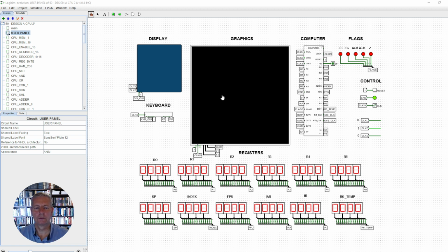I'm trying to do just one thing. I have a command which puts a little pixel on the screen. So the command is PIX, and then the next 16 bits tells it which input-output card we're interested in. So we'll see that just in a minute. And then the next 16 bits tells us what colour the pixel is, and then the next 16 bits tells us the X and Y position. So it's just pixel and then 3 numbers.